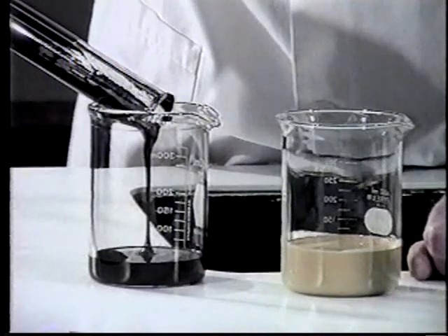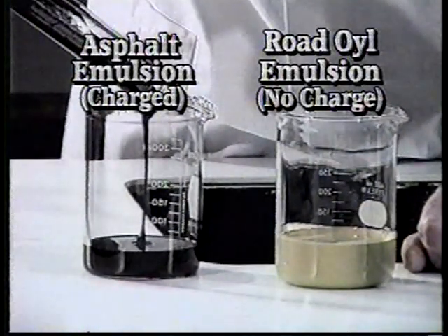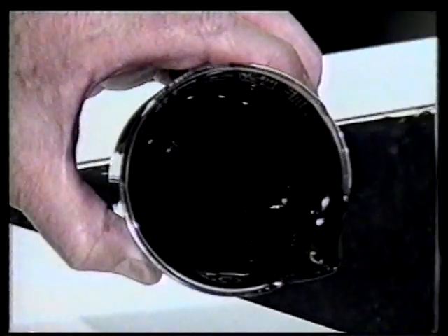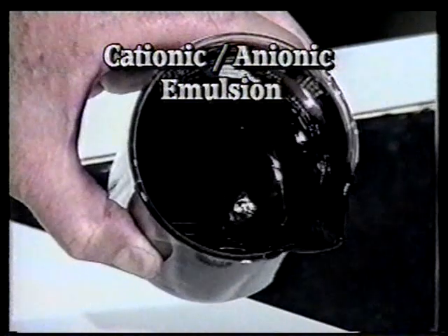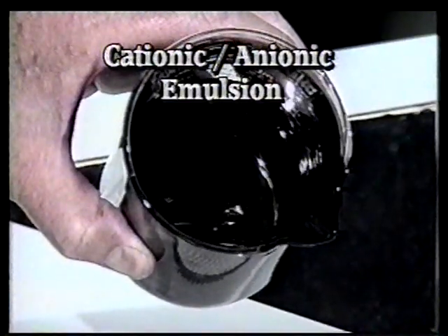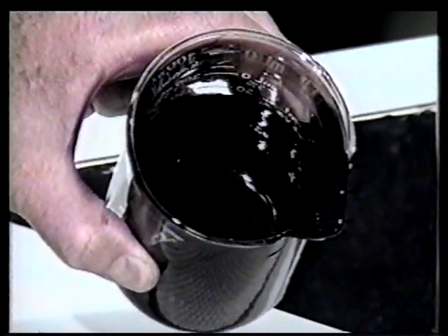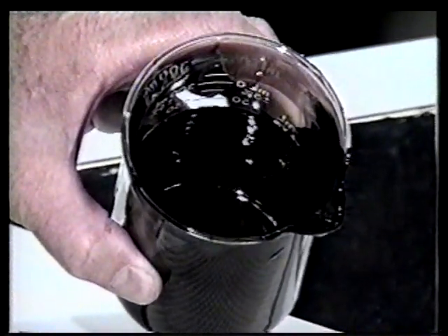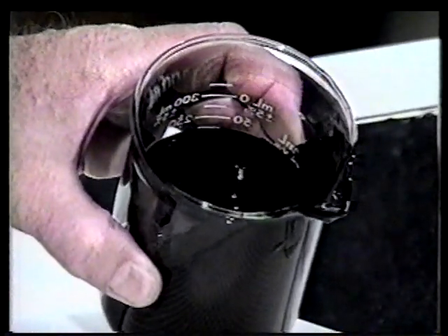Traditional asphalt emulsions and most other emulsion products require an electrical charge to exist as emulsions and to perform their ultimate binding task. Unfortunately, these charged emulsions, also known as cationic or positively charged, and anionic or negatively charged emulsions, come with a long list of trade-offs such as limited stability in storage, extreme sensitivity to the chemistry and clarity of dilution water, and sensitivity to the surface chemistry of aggregate materials.